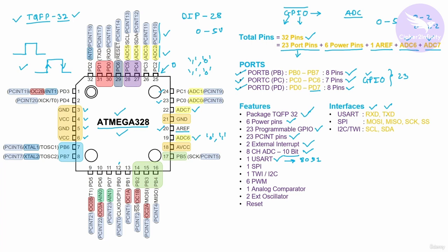Whenever you have to communicate with an external device that supports the USART interface, you can use the USART pins of the microcontroller. You will connect the USART pins of the microcontroller with the USART pins of the external device. For example, GPS receivers available in the market support the USART interface.